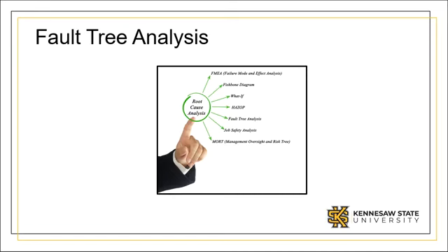Fault tree analysis is extremely useful during the initial product and design phase. It can also be used for safety hazards or requirements, system reliability, corrective actions, or troubleshooting. Fault tree analysis is preferred over FMEA where there is a safety or operating issue. Fault tree analysis uses logic gates to determine the overall reliability of a system. There are numerous fault tree analysis symbols. These are provided in technologies designed to create and characterize fault tree analysis investigations.